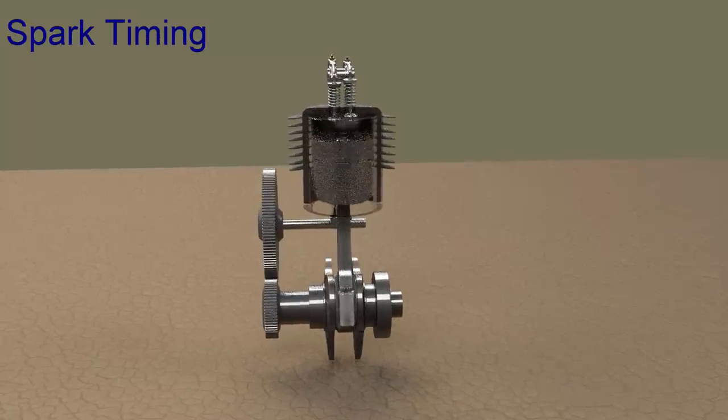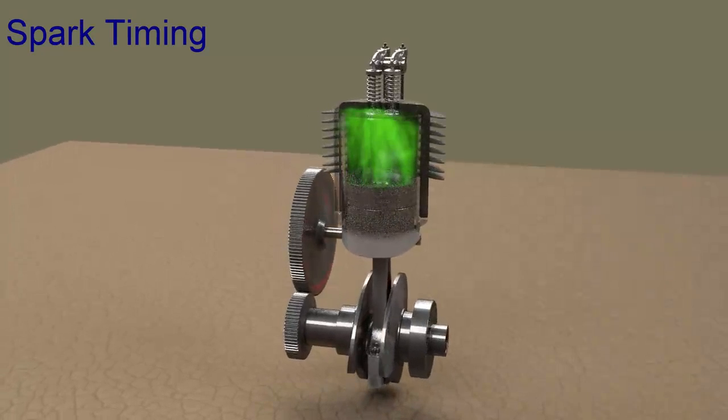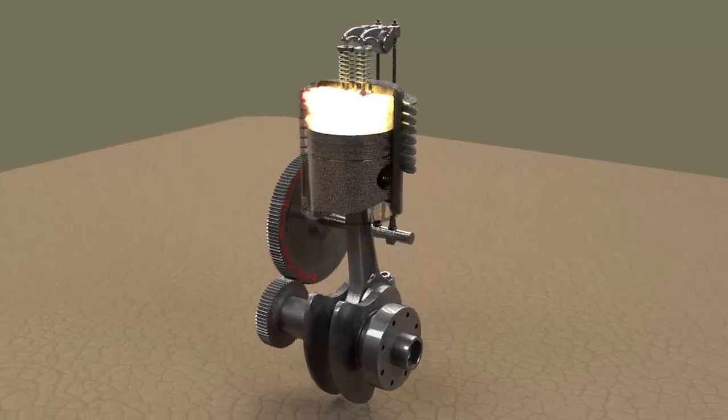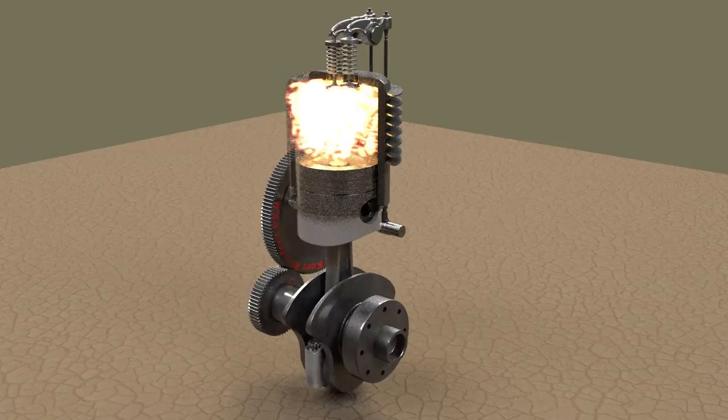The electric spark has to happen at exactly the right time or the engine will not run properly. For example, if the spark occurs much before the piston reaches the top dead center, the fuel will pre-ignite and the increased pressure may lead the piston to move in wrong direction, which will eventually stop the engine.